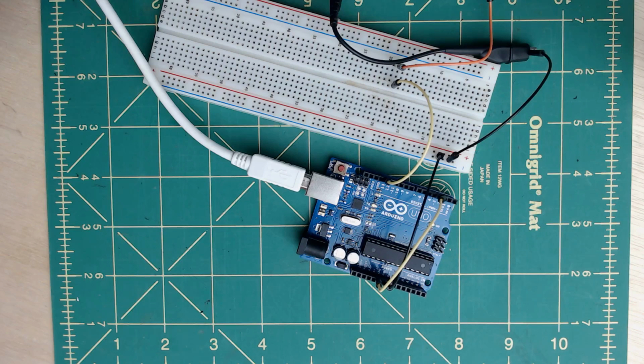So they have what are called pull-up and pull-down resistors. Now you can use external pull-up and pull-down resistors and tie them to your breadboard or whatever you would like to do. Pull-up and pull-down resistors are usually 10 kilohms, 50 kilohms. It's what's called a weak sway to one direction or the other. You don't want too low of a resistance value, or whatever's driving your pin will not be able to overcome the pull-up or pull-down resistor. And so what Atmel has done with these chips is provide a nice way. They include an internal pull-up resistor.